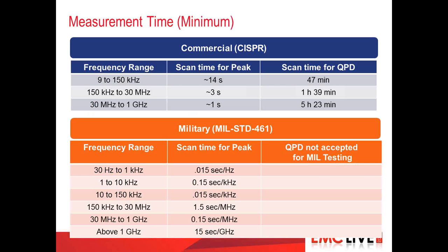To give you an indication of some of these measurement times, for commercial measurements, you can see in blue the scan times for the peak and also the quasi-peak versus frequency, and then the same for mil standard in the orange.